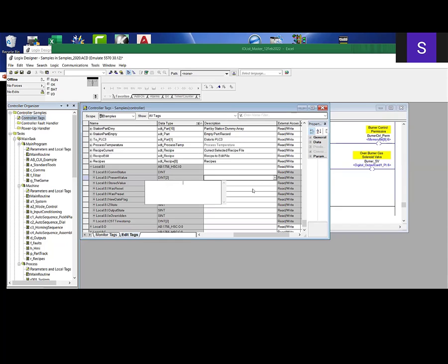And I could say, for instance, turn on an output if this present value was over a certain value, but you really don't want to do that because it's slower than using the physical output from the card itself. So people usually use an encoder input for 2 reasons. 1, it counts much, much faster than the PLC can. And 2, you can fire your output immediately rather than passing it to the PLC, waiting for the scan time, and then putting the output out that way. So hopefully that answers your question.